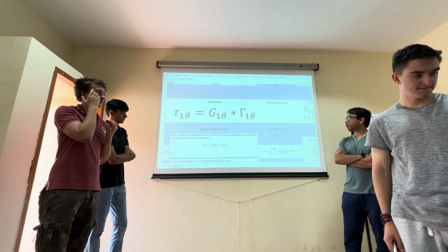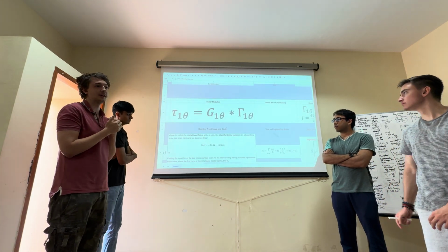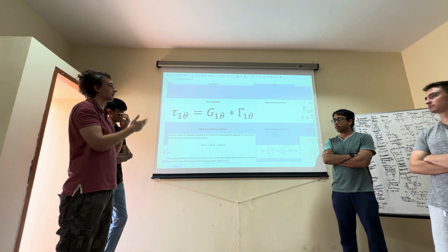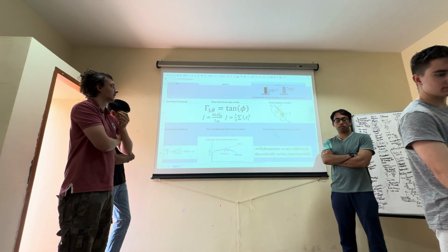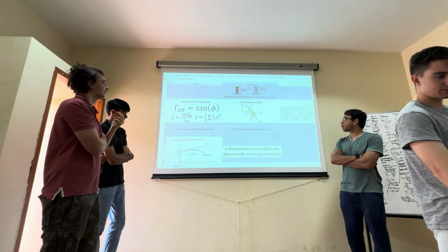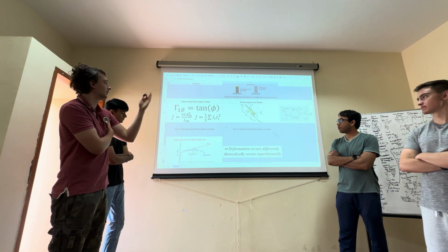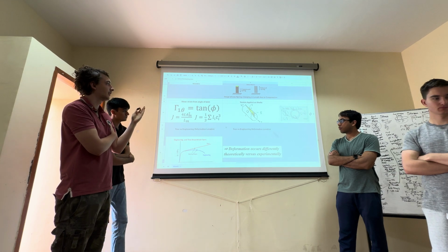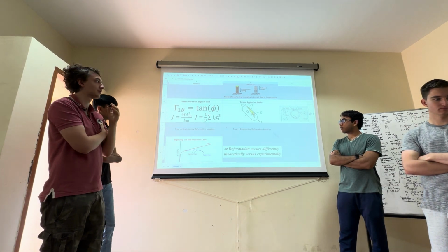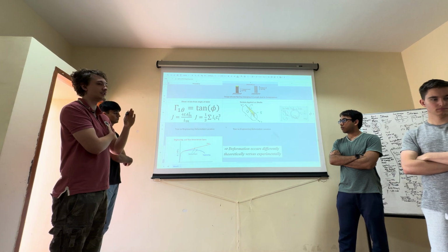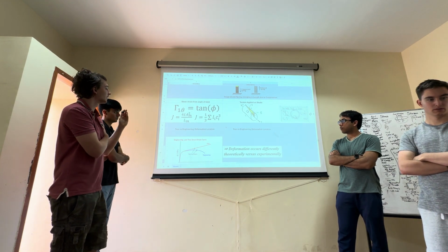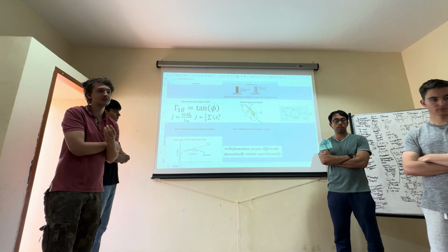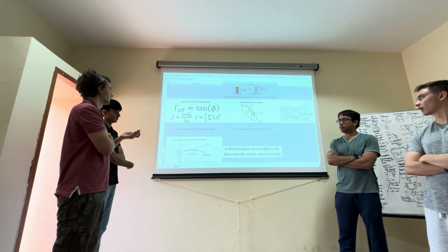And hence, using the formula for the shear modulus, we can relate the shear stress to shear strain. Then going further, we can relate shear strain to torsion applied in a shaft. So for this specific example, torsional strain will be tan of phi, phi being the angle by which the material shifted. And here are some examples of torsional coefficients for thin-walled cross-sections with uniform cross-sectional sides.